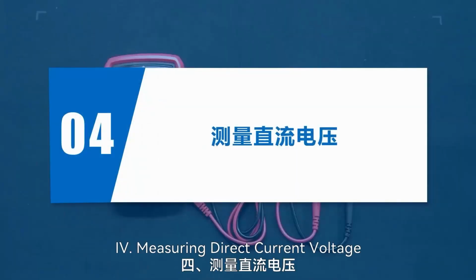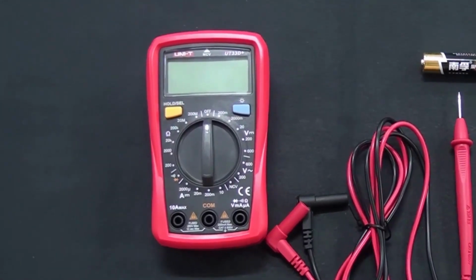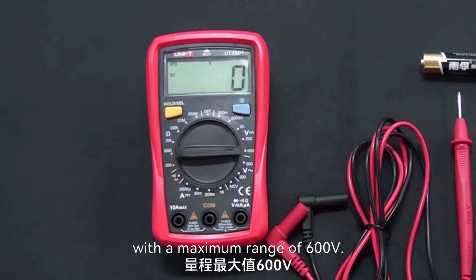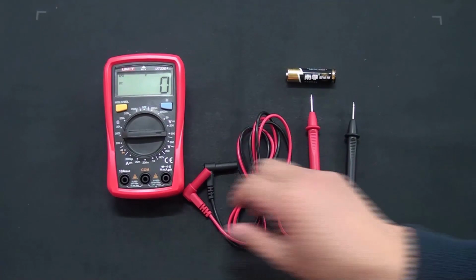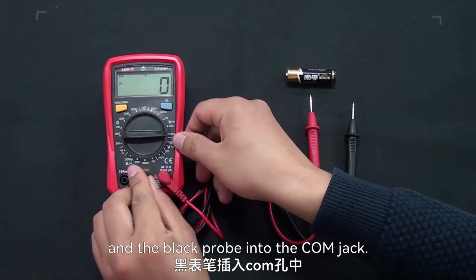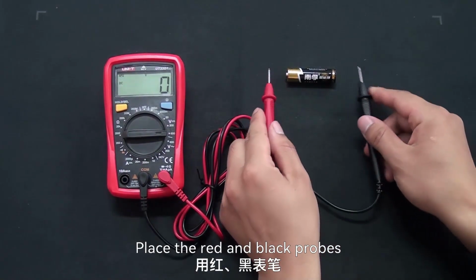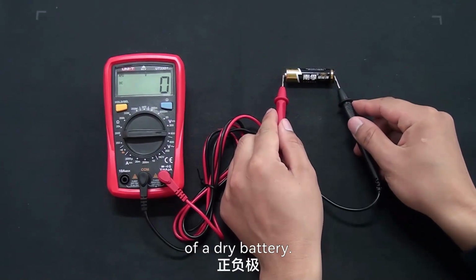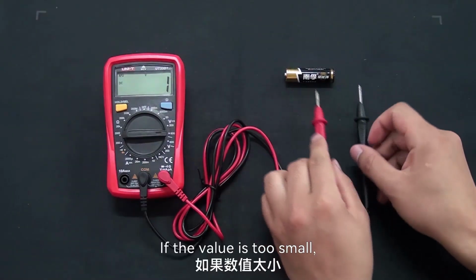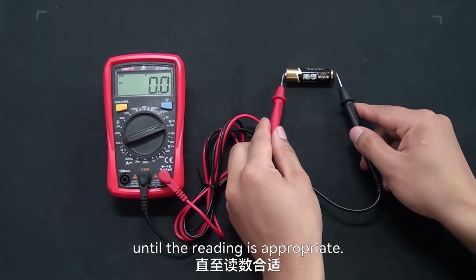4. Measuring direct current voltage. Choose the direct current voltage range with a maximum range of 600 volts. Insert the red probe into the volt-ohm milliampere jack and the black probe into the COM jack. Place the red and black probes on the positive and negative terminals of a dry battery. Read the displayed value on the screen. If the value is too small, for better measurement accuracy, switch to a smaller range until the reading is appropriate.